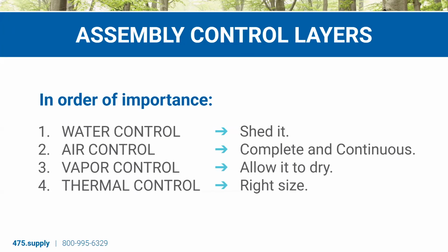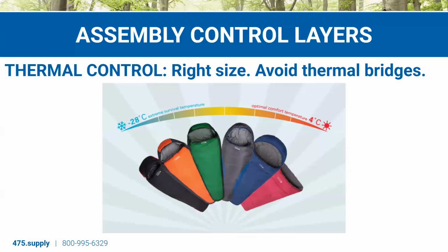This is going to be very different depending on your climate zone. Just like choosing the proper sleeping bag, we're adjusting what level of R value of thermal control we have based on our climate zone. So in warmer climates, we tend to need a lot less. In more cold climates and more northern climates, we need a thicker blanket. We need thicker insulation.